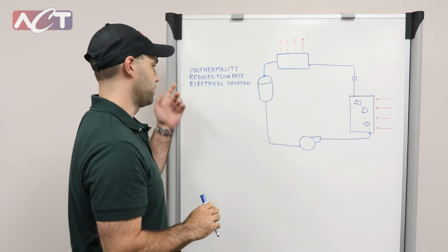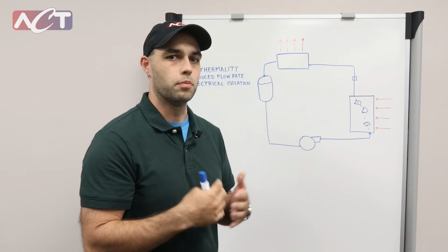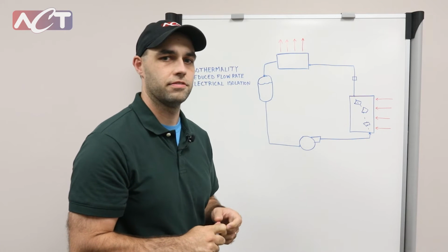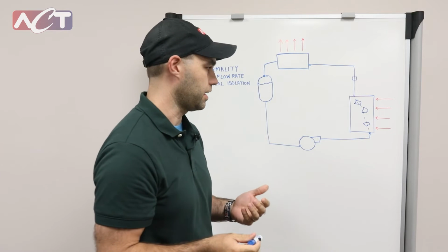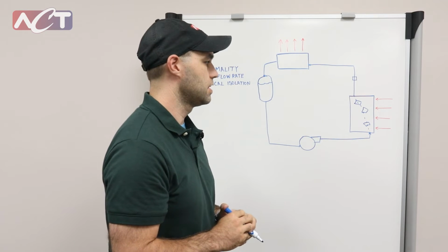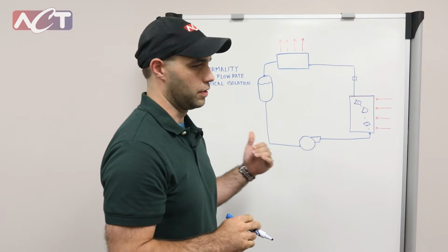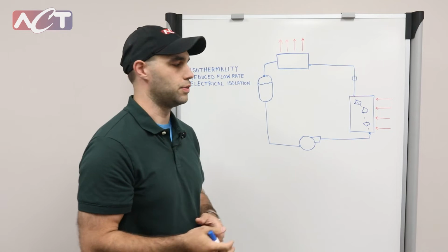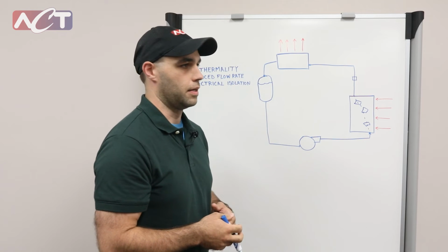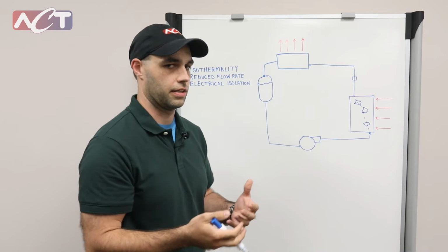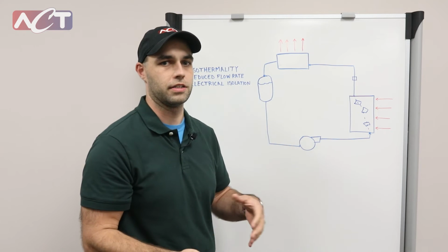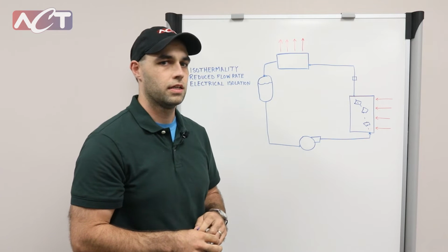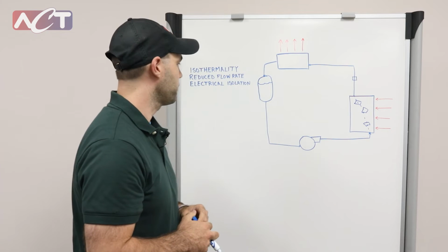The next advantage is a reduced flow rate, again because you're boiling the fluid. The latent heat capacity of the fluid is much, much higher than the specific heat capacity of most fluids. And so as you're moving through, the amount of coolant, like the mass of coolant that you need to take a certain amount of heat, is less. So that brings a lot of advantages depending on the rest of the system architecture. Your pumps can be smaller because you're moving less fluid. It can scale down other parts of the system as well relative to a single-phase system.